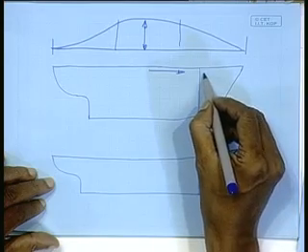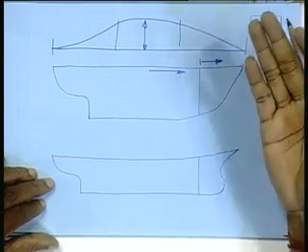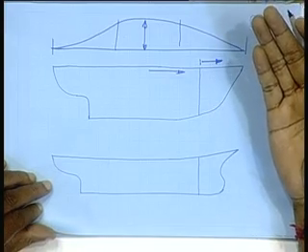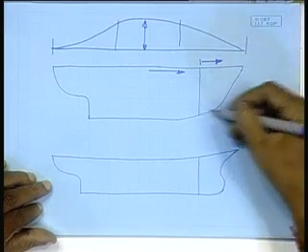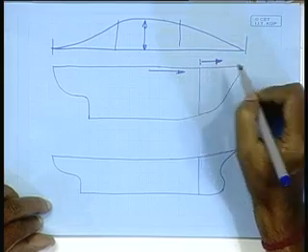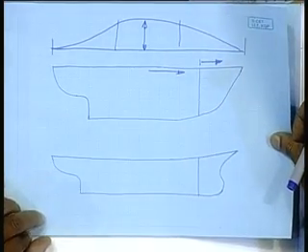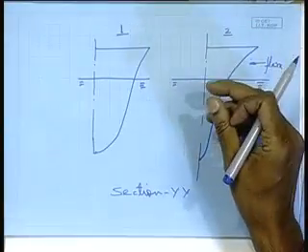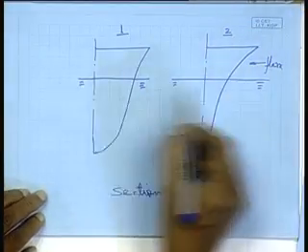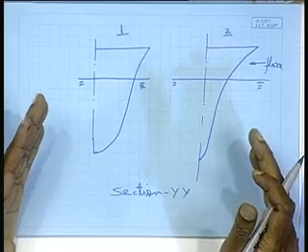But again when we go beyond a certain point and go further forward, then again we see a rise in the scantlings. That means it is no more the case of the stresses due to bending moment, but it is the local loading which comes into play, right. Local loading takes over.